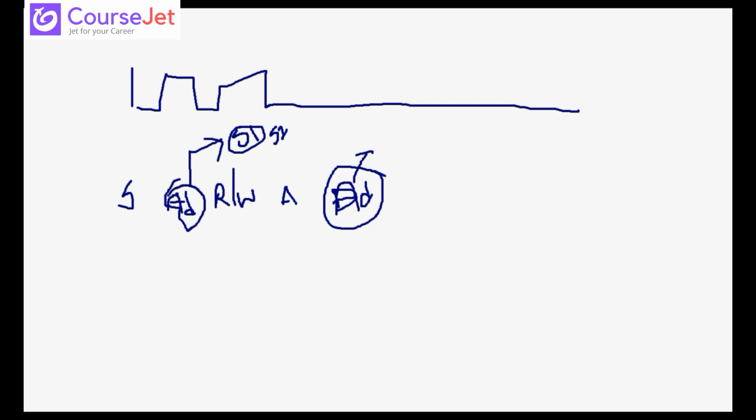So this address tells the device where the address location is, and then we give an acknowledgement. Here you need not say whether you want to write or read. Why? Because we have already mentioned that in this device we are going to do a read or write operation, so we need not say it again and again. After selecting read or write, simply give the address location and then send the acknowledgement bit. After sending the acknowledgement bit, whatever you send now is your data.